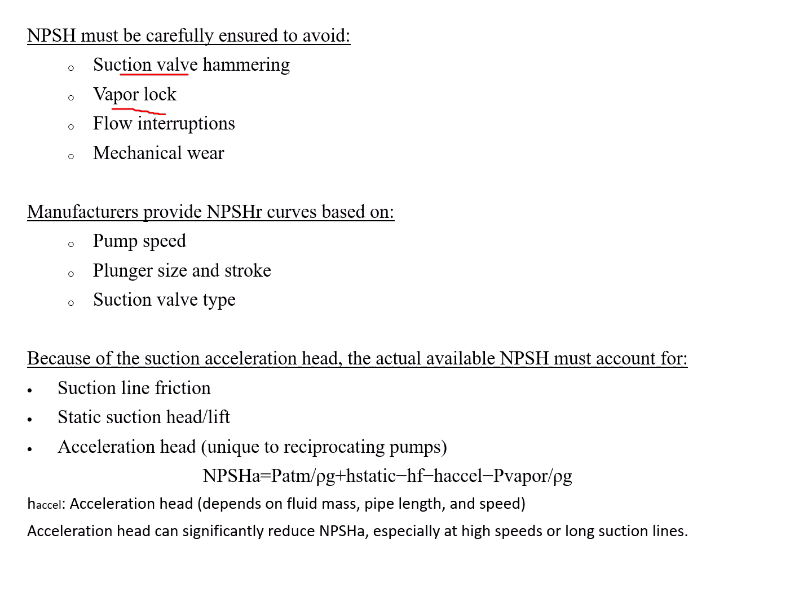Because of the suction acceleration head, as I just mentioned, the available net positive suction head must also account for suction line friction, static suction lift, plus the acceleration head, which is due to reciprocating pumps because there is acceleration. So the actual available net positive suction head must account for the friction, static suction head, lift, plus the acceleration head.